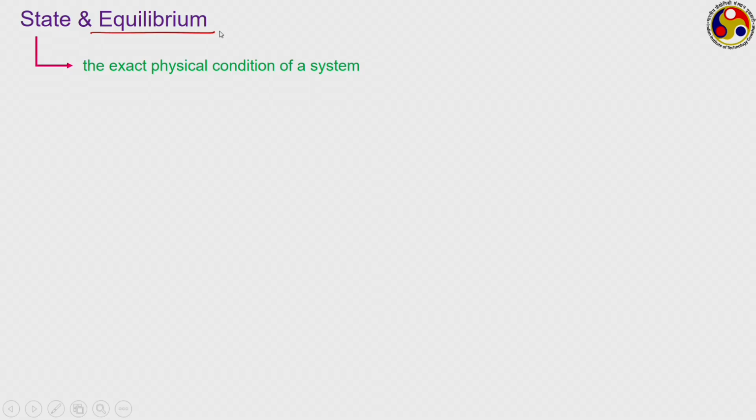Equilibrium state refers to a state of balance, that is a state where there is no unbalanced potential inside the system, because of which the properties are not changing. Or I should say that if a system is in thermodynamic equilibrium, then there is no unbalanced potential inside the system, and therefore, the properties of the system are not changing with time. They may also not be changing with space, as I am coming to that. But in thermodynamics, we always deal with the state of equilibrium.